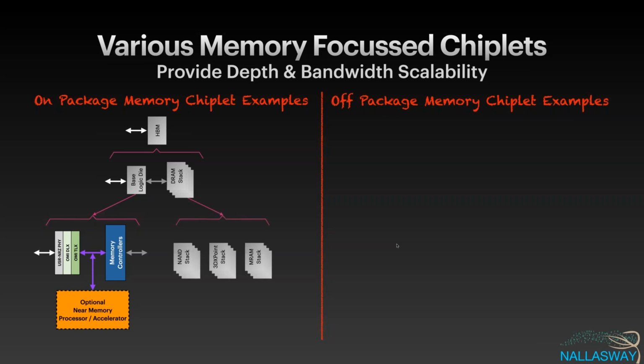Likewise, with this type of interface, unlike the current HBM interface, we could interface to a NAND stack or a 3D XPoint stack or an MRAM stack. And obviously the logic die would have to change. So obviously this is going to be 3D TSV type integration, which the big guys are really focused on. I think in Ali's block, these would be various blocks with a really expensive die stacking capability of the big guys, but they're in a granular element that a tier 2 and tier 3 can utilize. There's no way a tier 2 or tier 3 would ever create these, but they could utilize them. So I like the hierarchy that Ali's showing.